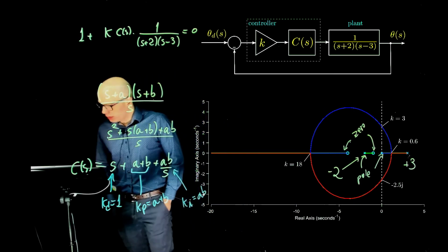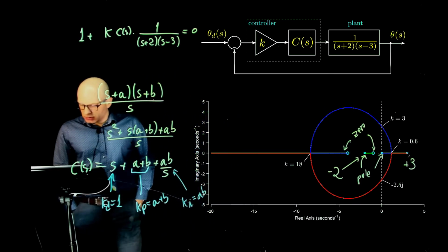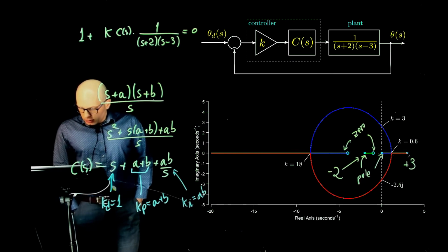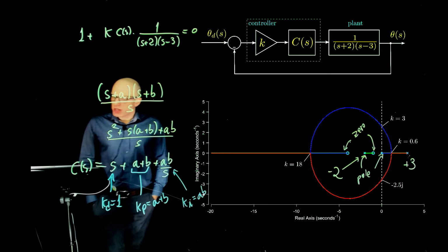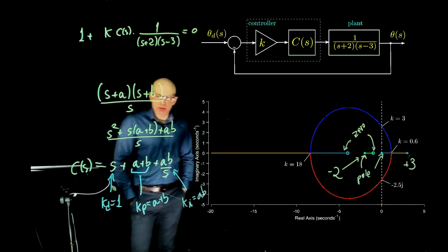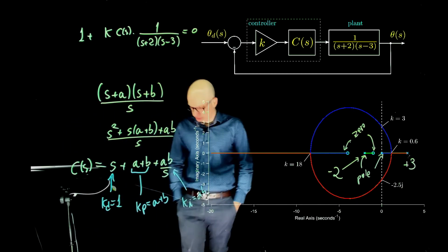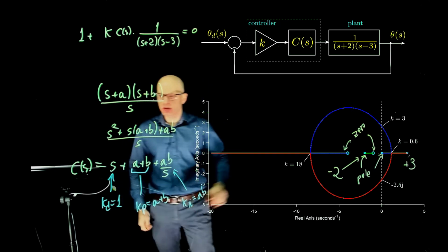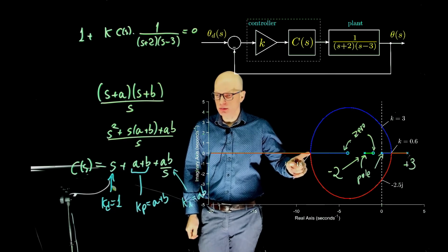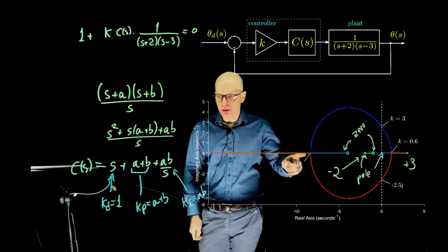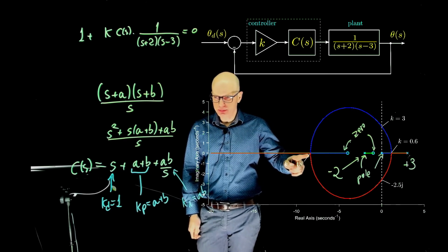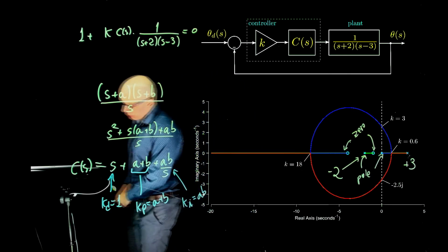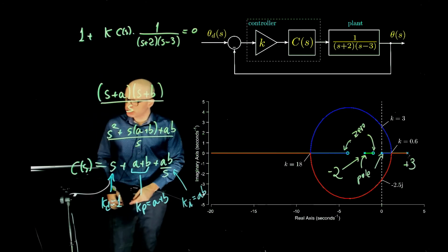Okay. All right, so the next statement is the system is stable for k less than 3. Well, that's false. Next one is when k equals 18, the system is critically damped. True. Right, when k equals 18, we are right here. The two poles are the same. And this characterizes a critically damped system indeed.